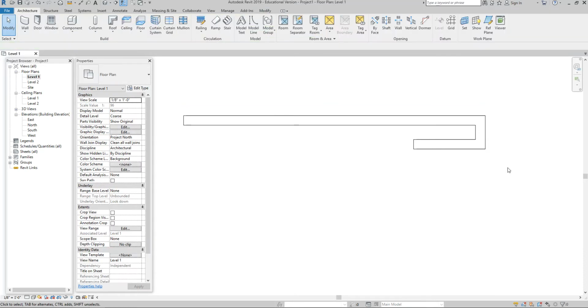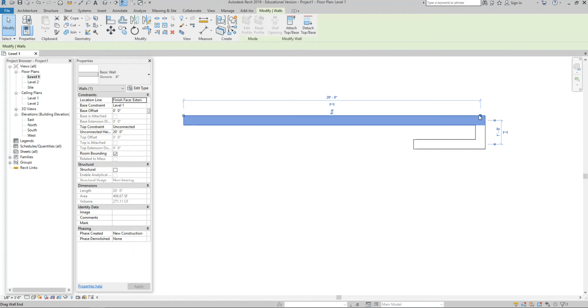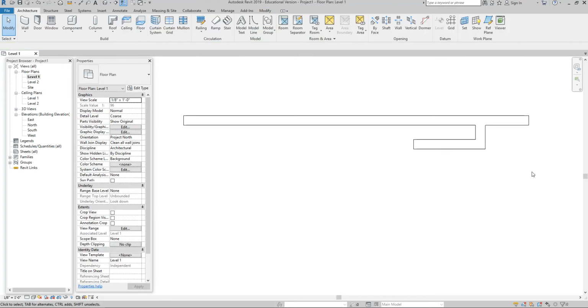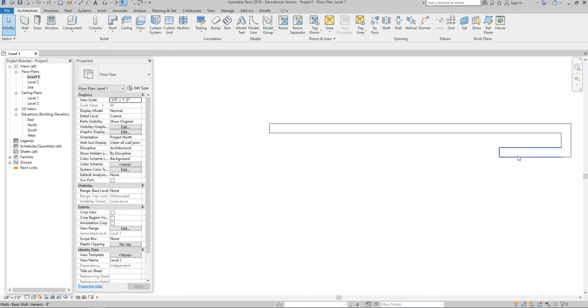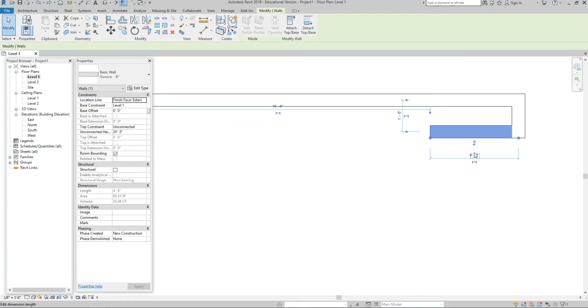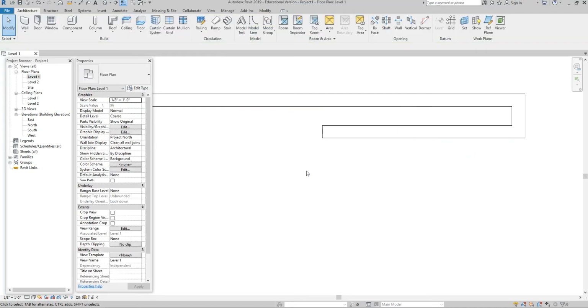If you lengthened it this direction, it would create a wall that doesn't make sense. It would extend beyond a connection point. So I'm going to hit undo, Control Z. So it's lengthening it in this direction. I bet it will do the same thing down here. So 4'6", if I click and type 10 foot, enter, it lengthens it at its free end.